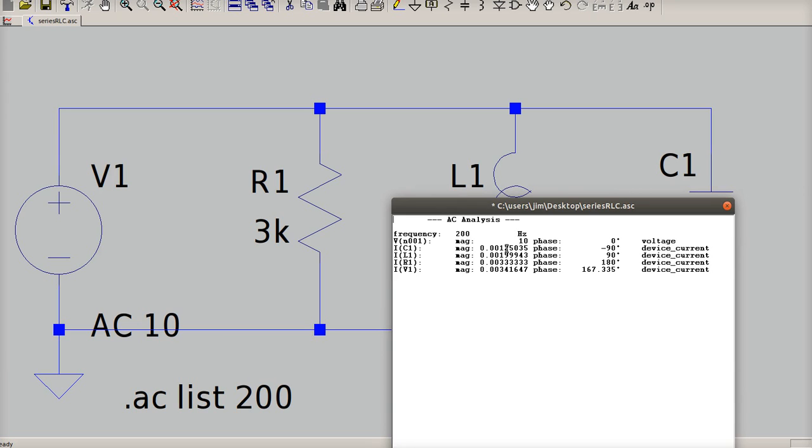Scilab, if you go through and do the calculation, for each of the voltages, it's coming up with that and then it's adding it. And as you can see, it's not a pure add, because in polar you get this current added to this current added to this current, and you don't get this because of these angles. The angles matter. If you convert these all to rectangular and you add them up, you'll get what I got, rectangular. So sometimes it's easier to work in polar, sometimes it's easier to work in rectangular, depending on what you're doing. So I hope you get a sense of what's happening there.